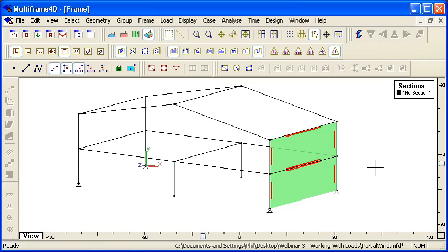And then we have our load panel properties toolbar here, and so we can show which sides of the load panel are supported. So you can see that by default it has put the supports for the members around the side, and as a consequence of those side supports we can then automatically show the tributary areas, so you can see that the load within each of those tributary areas is attributed to the member supporting that side.